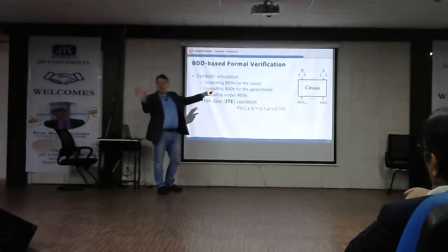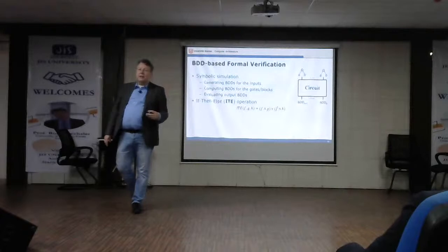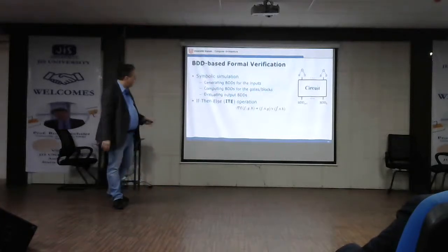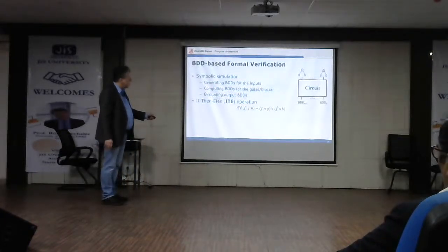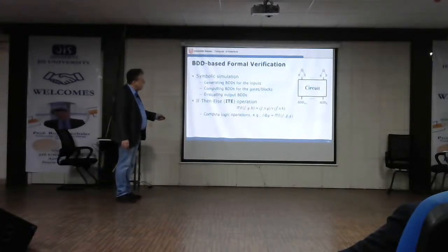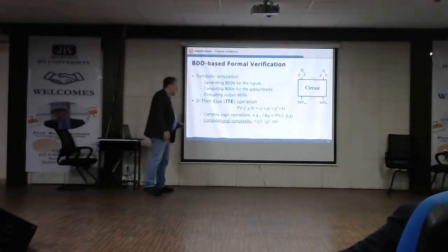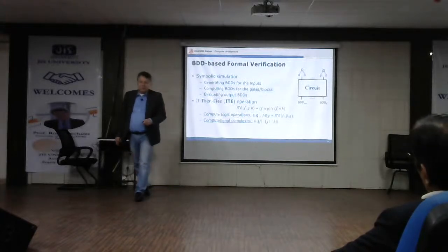For those who want to experiment with BDDs, you can download many free BDD packages on the internet. Yes, so this is freely available. And they are based on a so-called if-then-else operator. Based on that, you can formulate each of these internal gate operations in terms of this if-then-else, and this one also has a polynomial upper bound.